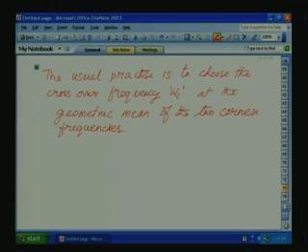Okay. Now, from our previous example, we can approximately choose Tn equal to 4 delta. We found we can use that one here itself also. So, if we choose 1 by Tn equal to 1 by 4 delta, we are already choosing this approximation. Usually, this 1 by Tn should be away from the 1 by delta, by a factor of 5 to 6. So, if you take 1 by Tn approximately equal to 1 by 4 delta,